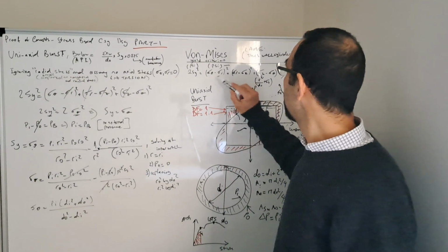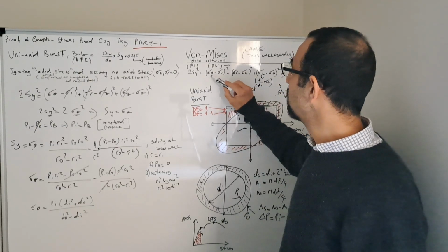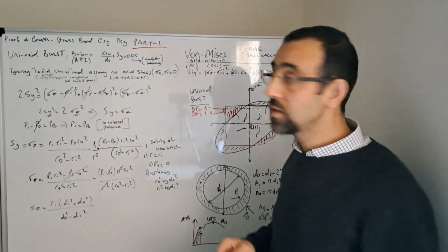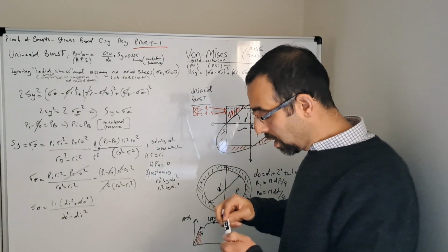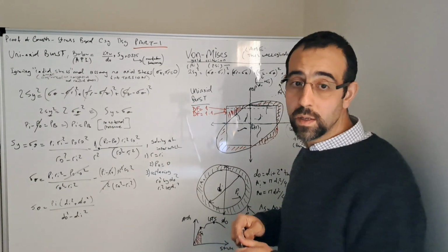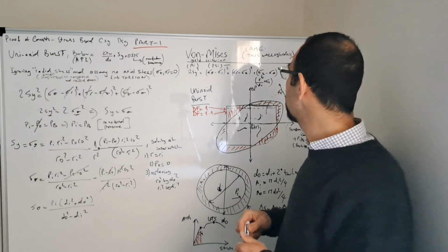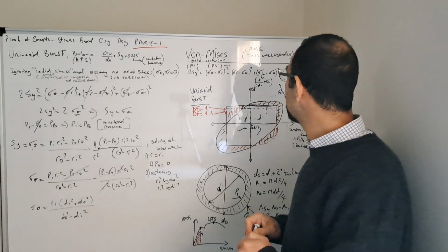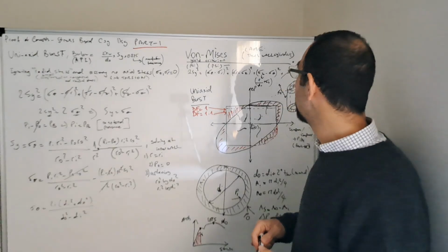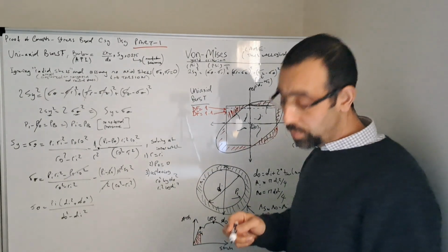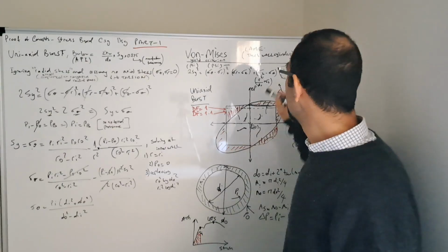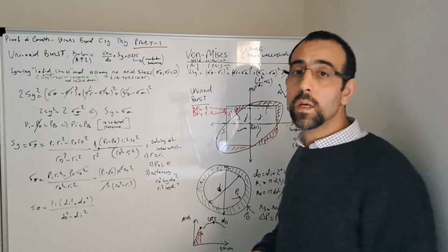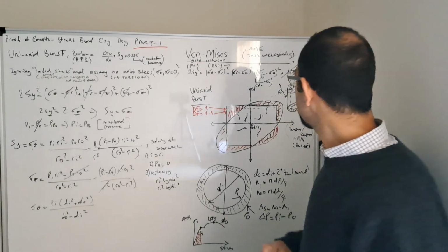So on the right-hand side we have the principal stresses, tangential stress and radial stress, whose derivations were made by Lame, and they are historically referred to as the Lame equations for the thick wall. And we have the axial stress, which is the tension or compression divided by the cross-sectional area, to convert it to psi from pounds. And we also account for the bending, which is due to the doglegs in the well.